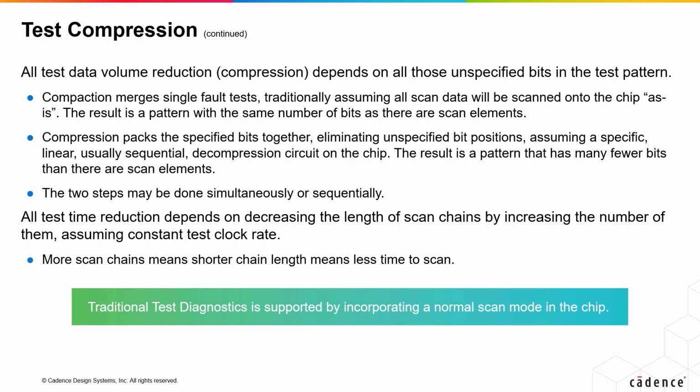patterns. By adding logic on the chip that decompresses the test data with a known algorithm, the single fault tests can be merged, using the inverse algorithm, to create a much smaller set of test patterns. This depends on the compression-decompression algorithm being linear and reversible. The decompression could be combinational, but most algorithms assume a linear sequential circuit very similar to the pseudo-random pattern generator